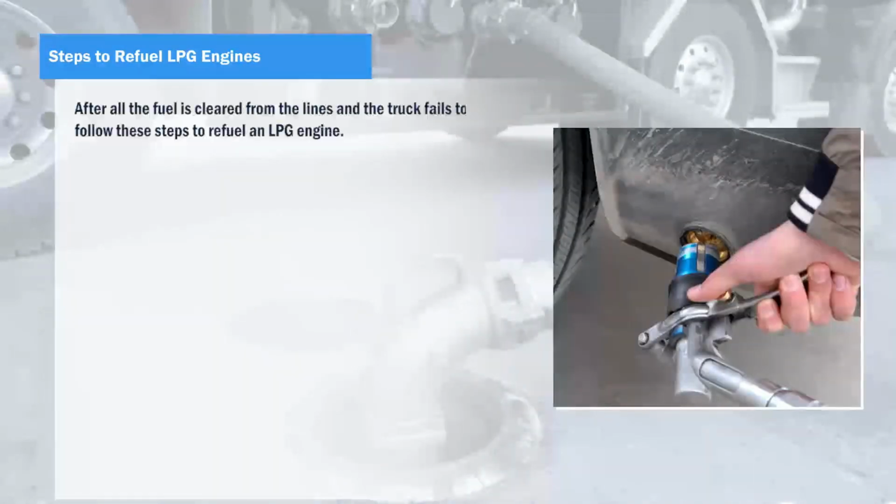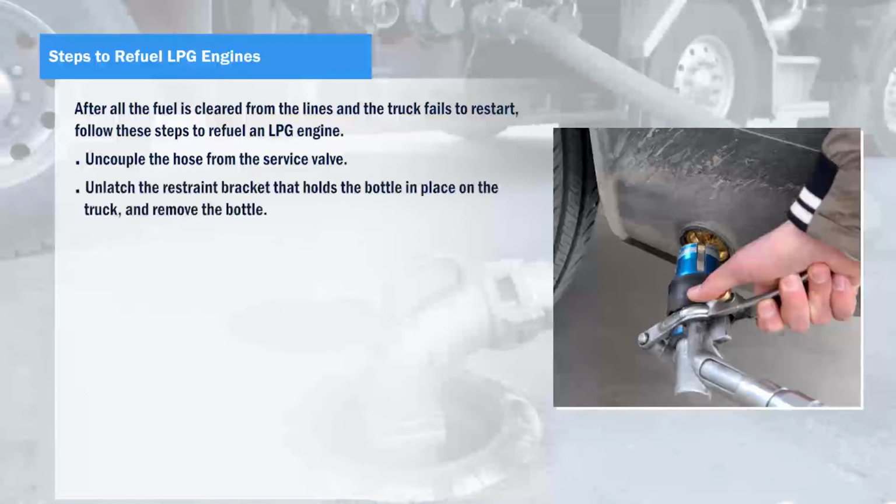Steps to refuel LPG engines. After all the fuel is cleared from the lines and the truck fails to restart, follow these steps to refuel an LPG engine. Uncouple the hose from the service valve. Unlatch the restraint bracket that holds the bottle in place on the truck and remove the bottle.